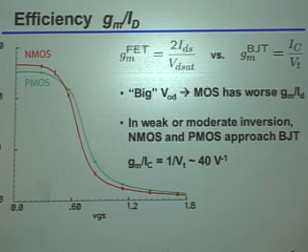That is largely surprising for people who have been doing this for a very long time, but nonetheless, that is the way things are going. So, in general, PMOS is slower than NMOS, but don't take that as a universal truth. Really, the more important point is that it's not typically the transconductance efficiency that's different between the two. It's the intrinsic speed you can get out of them that makes a much bigger difference. Okay?